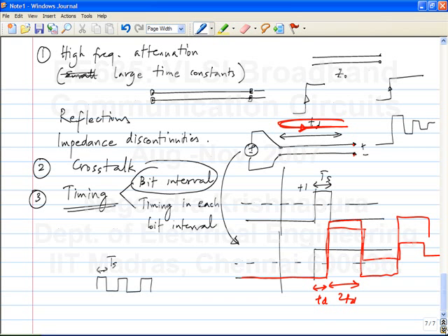So similarly for multiplexing or demultiplexing, whether you want to have one wire operating at a high frequency or many wires operating at low frequency, it's also a matter of cost and how complex it is and so on. So if you choose the highest data rate and choose only one wire, it uses the smallest amount of infrastructure, but it's also most complicated to do signal processing and recover what was being sent. Now if you have a whole bunch of wires at a very low data rate, it's very easy to recover the data, but then it becomes too expensive because you have to have a transmitter and receiver for each one of them, and that may be too expensive. So there are both cases, okay? So in practice also.